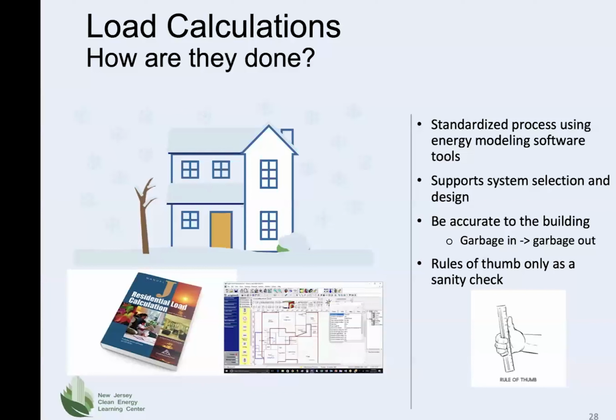Many of the software programs that are approved by the ACCA include local weather data that designate the design outdoor air temperatures for heating and cooling used to perform the load calculation. The collection of data for a particular home that is used as an input value for the load modeling must be done carefully and completely in order for the program to calculate precise thermal loads. The rule of garbage in, garbage out is applicable. If the inputs are incorrect, then the output will be incorrect.